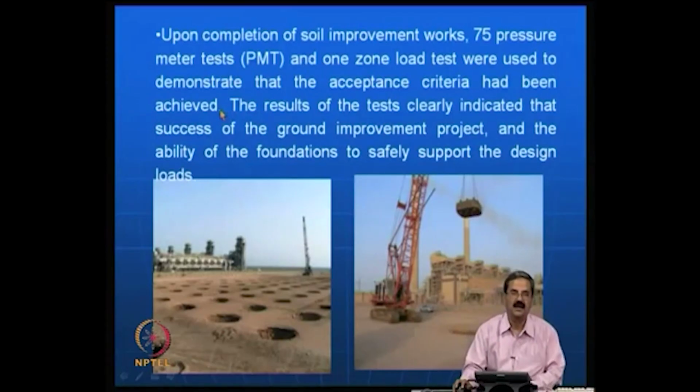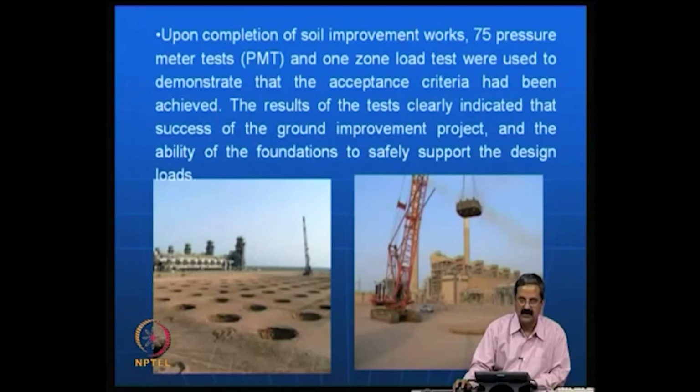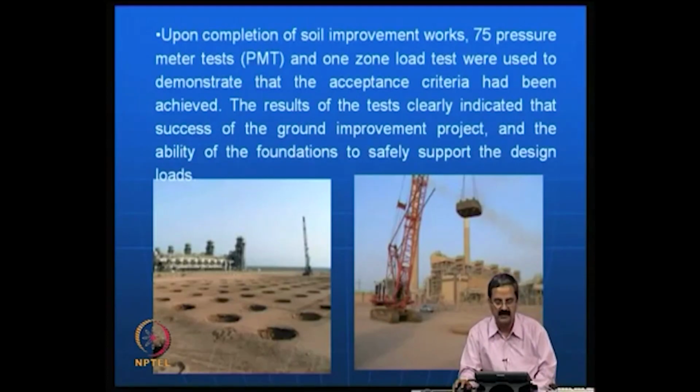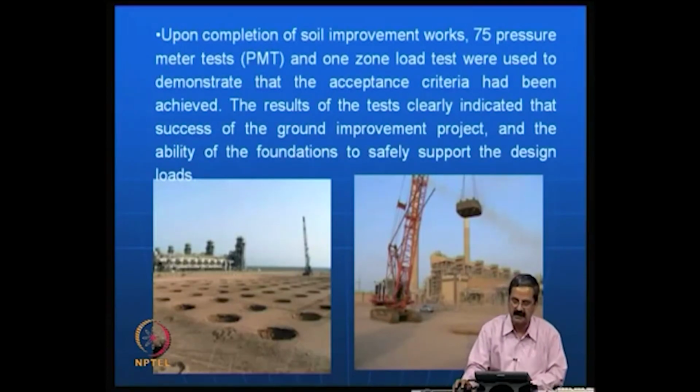For example, what is the acceptance criteria? The bearing pressure and settlement. From the pressure meter test you get a parameter called limit pressure. Limit pressure is related to bearing capacity, and settlements can also be calculated. So the acceptance criteria of settlements and bearing capacity are met using this. The results clearly showed the success of the ground improvement and the ability of the foundation to safely support the design loads.